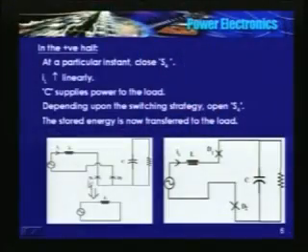See, in the previous transparency, when I closed in the positive, of course input is still a sinusoid, but the voltage across AB, or VAB, is 0. This is A, this is B. See, S4 and D2 are conducting. This is point A, this is point B. So they are connected together. There is a short circuit. So VAB is 0.